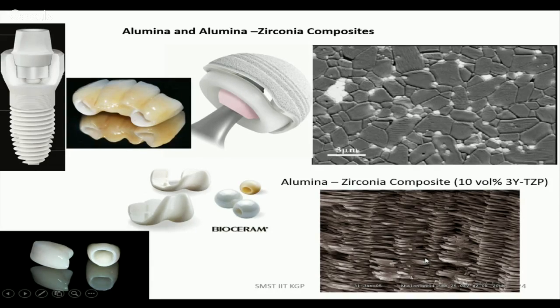Lithium disilicate and lithium aluminosilicate are the materials. There is a possibility to grow such microstructures. It has an intercalated platelet-like structure, and it can take an enormous amount of load. And because of intercalation, the crack doesn't follow a straight line. Rather, it goes zigzag, and that is giving you toughening.